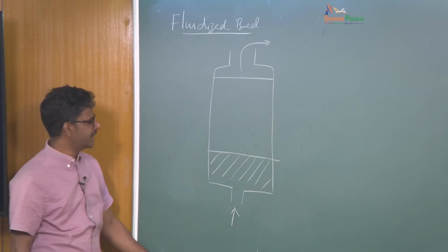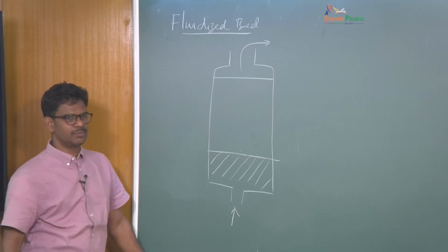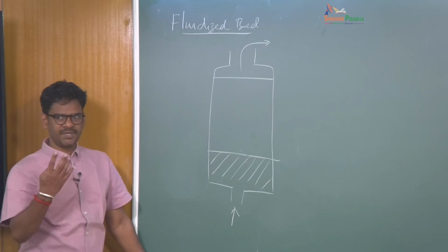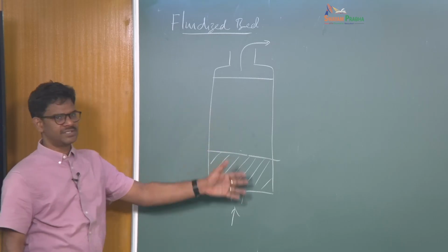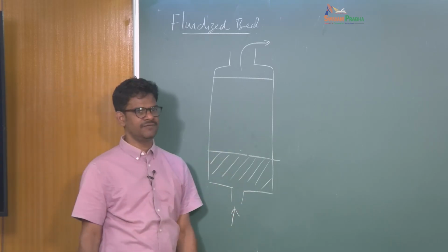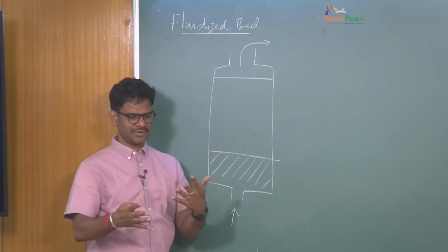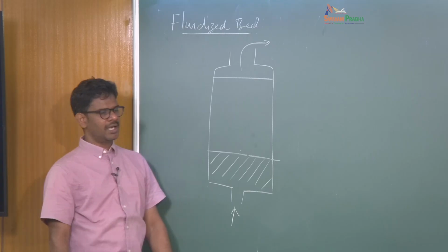So that is a different kind of model, and the conventional way of modeling the system would be again applying hydrodynamic theory, a hydrodynamic model, and studying mass transport and heat transport coupled with a reaction. You generally have something called multi-phase flow, right? You've got a gas, you've got a solid, and then reaction between them at the interface.